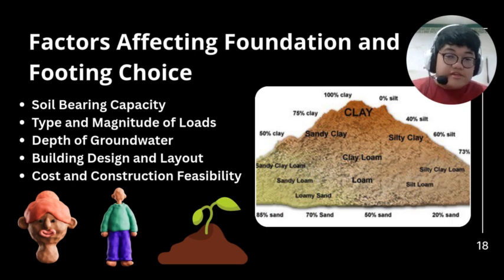Factors affecting foundation and footing choice. There are five: soil bearing capacity, type and magnitude of loads, depth of groundwater, building design and layout, and lastly, cost and construction feasibility.